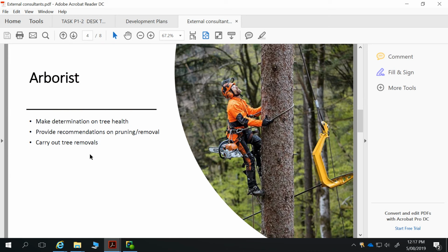So, the other thing I didn't mention, you're not always going to get a surveyor out. Sometimes you're going to have the contours to the accuracy that you need them to be. Right? On a flat site, you're not dealing with much. You could go around with a laser level and go, okay, we've got this amount of fall here, we've got to account for that over our footings, that's fine. In many instances, you won't actually require a contour plan.